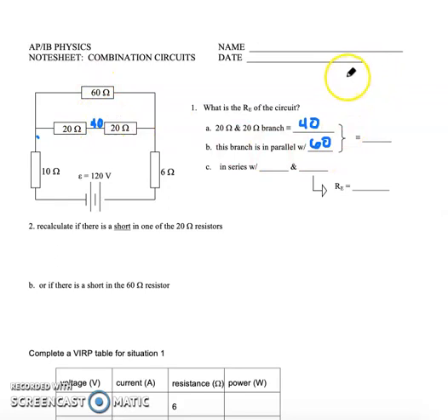Well, the equation for effective resistance for parallel, I'll do it up here, is 1 over 40 plus 1 over 60. All right, common denominator for these two is 120. This becomes 3/120ths. This becomes 2/120ths. 3 plus 2 is 5. So this becomes 1 over 5/120ths. You do the math, and that gives us 24 ohms. Oops, I should write it here. So the three resistors that are in this part reduce to 24 ohms. Again, double check that yourself to make sure you get that.